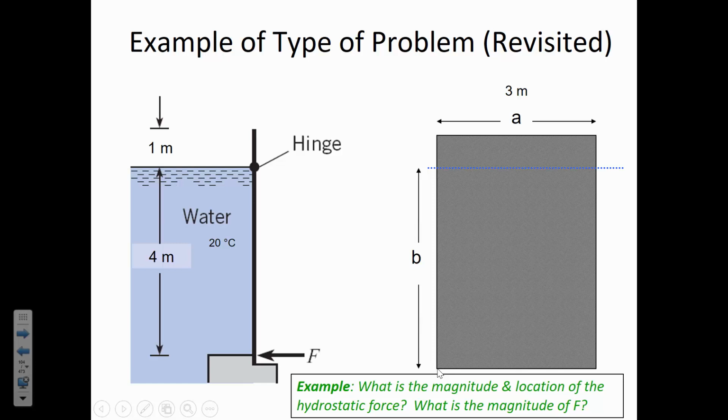So that's what the pressure is at the centroid of the plate. Now step 3, what we want to find is the hydrostatic force magnitude. So let me just transfer this little sketch here. We've got 4 meters by 3 meters. And the water is up to the edge.